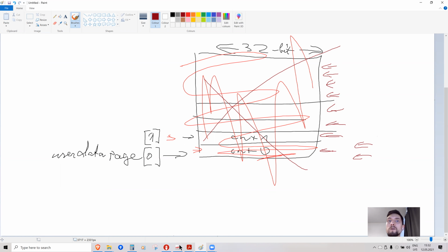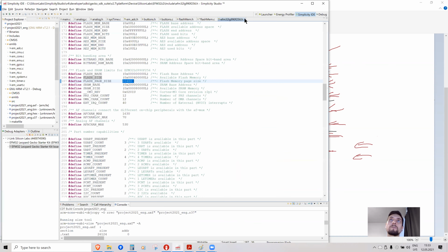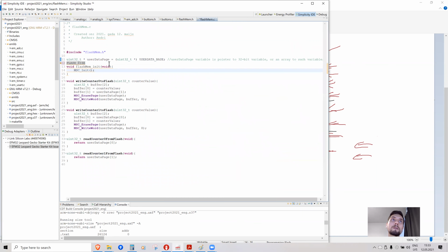So it's a 256 times less frequently done process, so the flash memory would wear off much slower. And of course, all modern operating systems and computers implement some flash wear leveling. So normally you would upgrade this code in such a way that you would have flash wear leveling.